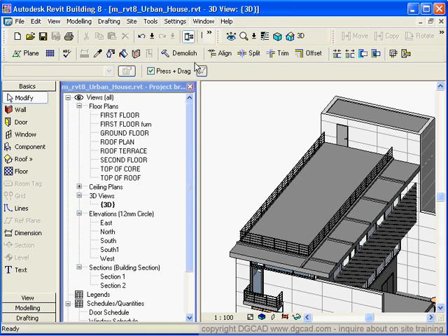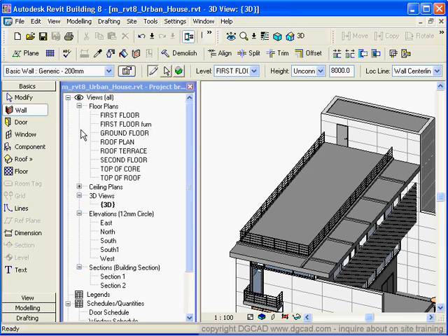And so we've got our toolbar section over here, and this dynamically changes. If I click the wall command, we'll see that this dynamically changes. This up here will stay pretty much consistent, and this is where we've got our offset and our trim and split and align. We use these all the time, many times a day. We've got some really nice object painters and Revit special painting tools over here when we want to draw linework. Our demolition object, which means the object will be demoed or removed or phased. And then over here we've got our design bar.